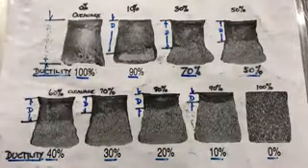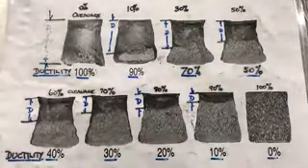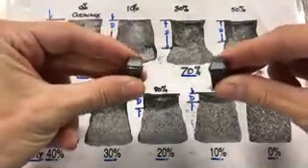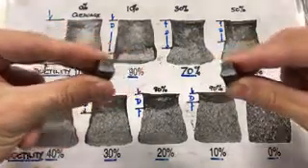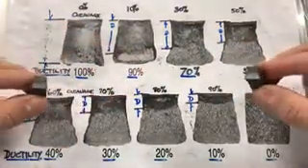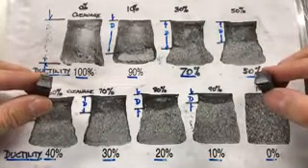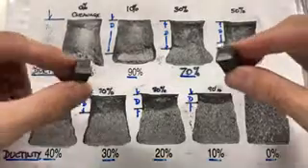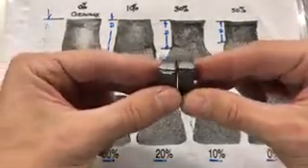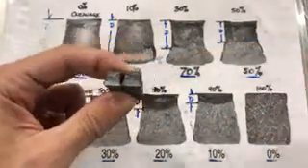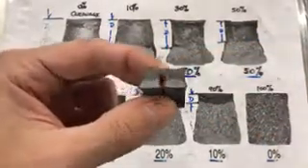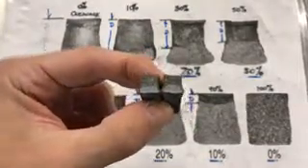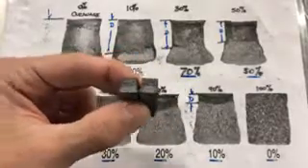Okay guys, in this quick video I'm going to show you how to interpret the fracture surface. You remember we got our sample and there was first piece of information associated with this sample, the amount of energy that was absorbed during fracturing, and that was 150 joules. So the next piece of information is how much ductility or cleavage we see in our sample. In other words, how ductile it is relative to its appearance of its fracture surface.